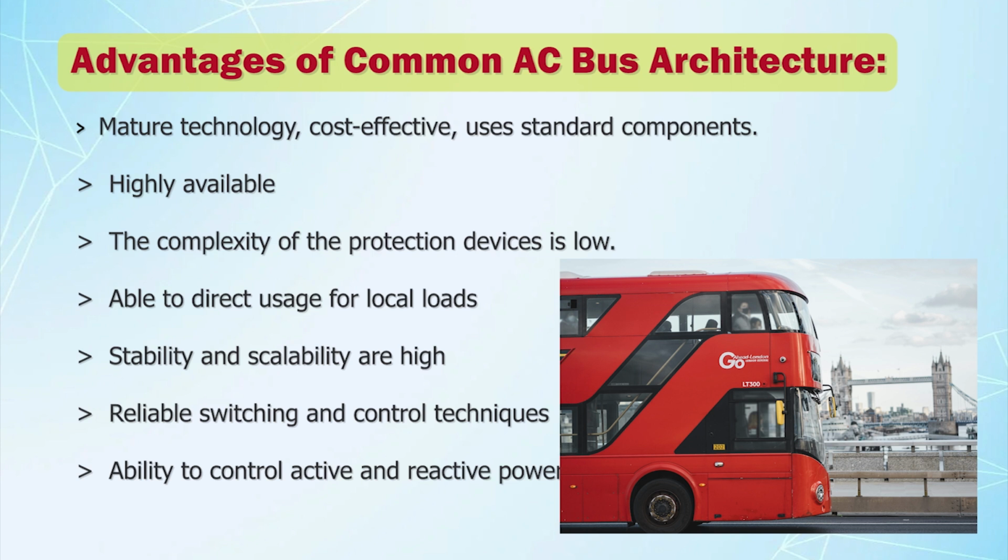So, if you observe the conventional charging station, there are basically two stages, one is AC to DC and another is DC-DC. The DC-DC stage is responsible for controlling the battery parameters. However, this AC-DC converter or DC to AC converter can be utilized to compensate reactive power.